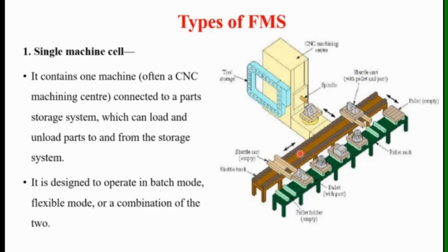Okay, and the material handling system, and this component goes onto this machine. The machine performs some operations on this, and again it is thrown back onto this system, and this component is finally unloaded from here. Okay, so this automated system is only for this single machine. So this type of layout is called a single machine cell.